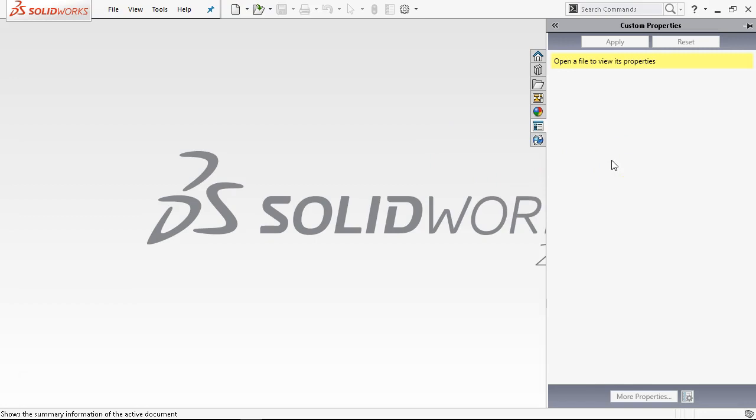a little interface that will have some selections, have some logic built into it, that we can put in part numbers, that we can put in finishes, things that we would want to track, and have it write back to the file properties so that each part carries that metadata with it. And then when it goes into the drawing, that's what populates our title block. I shouldn't have to type one thing into my title block because I put it all into the part. I put it all into the assembly, or most of it anyway.